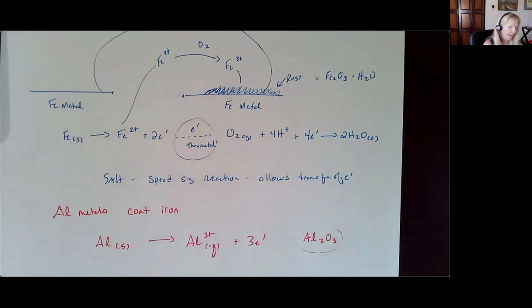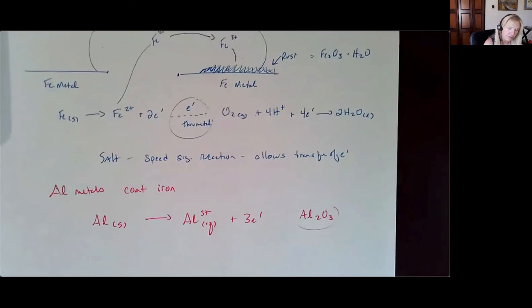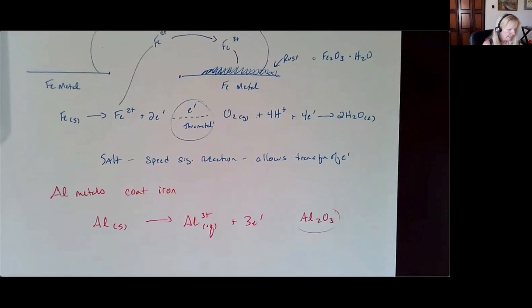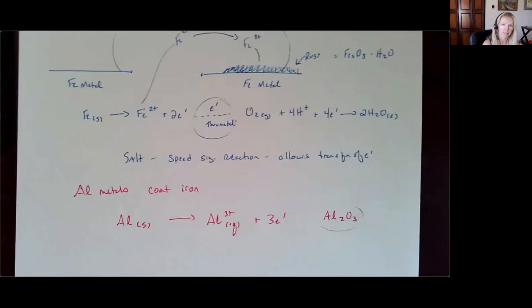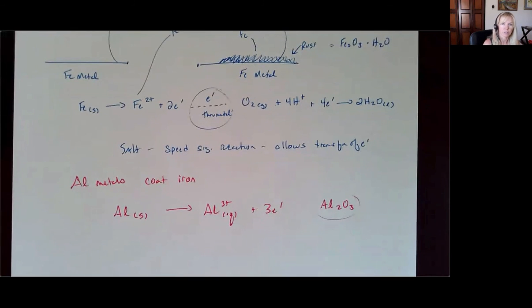So that's when we galvanize steel, metal. Galvanized is usually using zinc, molten zinc, and so you take the nail and it's dipped into molten zinc so it looks really shiny. You don't have to fully coat it as long as the two metals are touching, but it's more easily oxidized, so the zinc will corrode first, as opposed to the steel that's making up that nail. So that's what a galvanized nail is. Usually zinc is the coating that's on there that allows the zinc to oxidize over the steel of the metal.